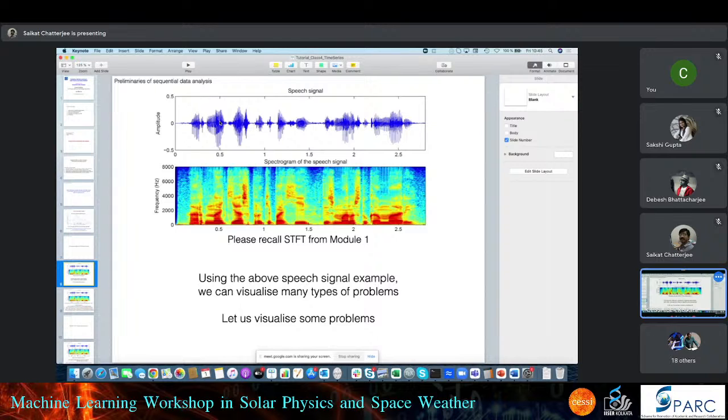Okay, and due to the modulations of speech in the generation of speech through our speech production system, this modulation changes, and that's why every sound becomes distinct and different, and that we can perceive, right, through our ear, through our listening. So now what you do, there is a tool called short time Fourier transform. The short time Fourier transform is a small window, and for a small portion I would like to find out what is the frequency component of that. So it's nothing but a spectrum of a short window.